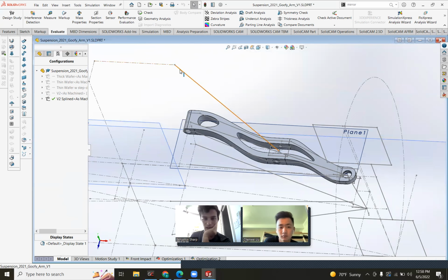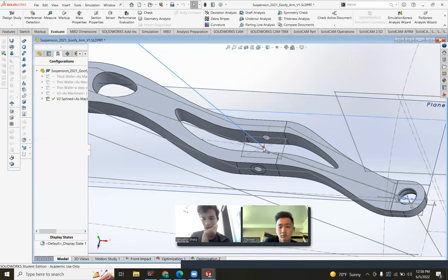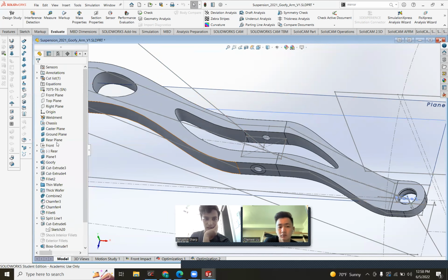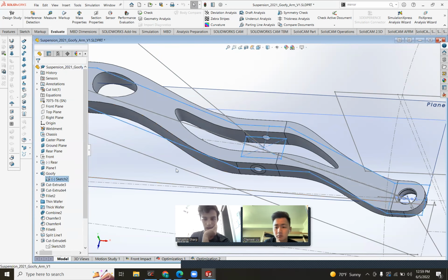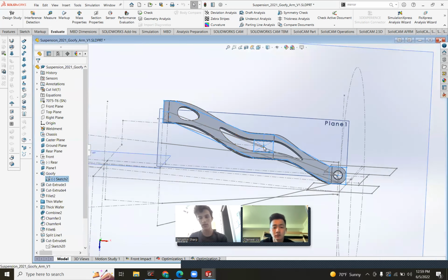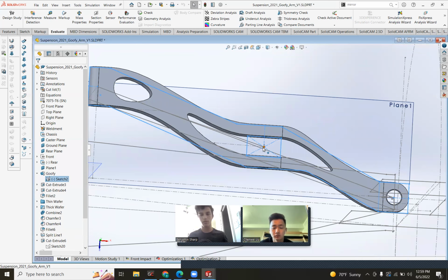You can move where the shock is mounted, front or back, and it just causes this mounting hole to change, which would push this entire sketch back. Like this box would be pushed back or forward based on where the shock is mounted. So you have a bunch of freedom there. But you should try to keep it generally along this path because it's better for loading. This path connects the center of the mount to the center of the spherical bearing. So you can see they're pretty close.